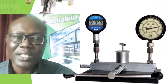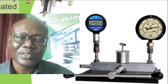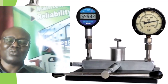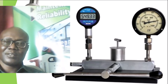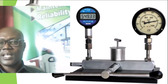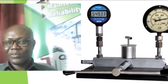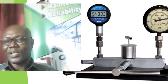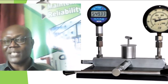So when we say calibration, what do we really mean? When we say calibration, what we do is that we subject the instrument and another instrument of known behavior, of trusted responses, to the process variable that we are actually measuring with that instrument.